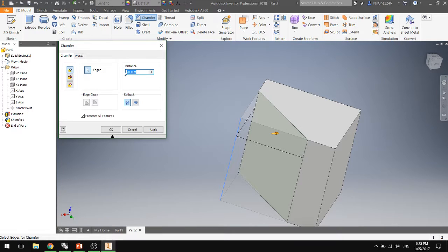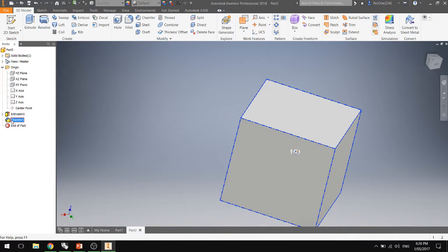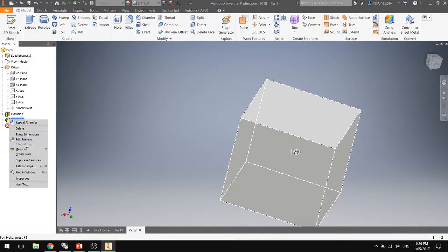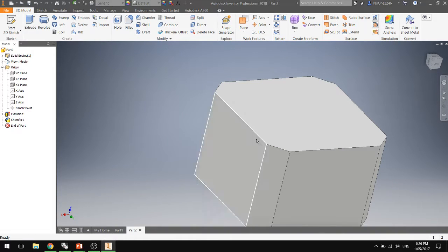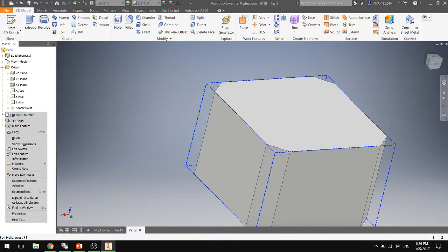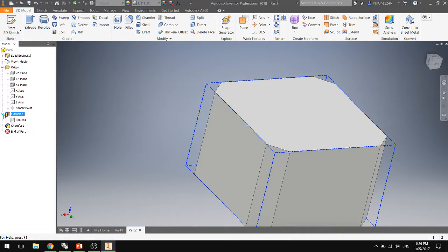Go to the left-hand side panel. So there, you can see the chamfer already before I started. Okay. Since we've already applied a chamfer, we can go here and edit something that we've already started doing. So we chamfered at 20 millimeters, which was actually the limit, and it resulted in a square box for us. If we change that to about a 5 millimeter one, it results in this. So here on the left-hand side, you can go in and edit each part as you go.